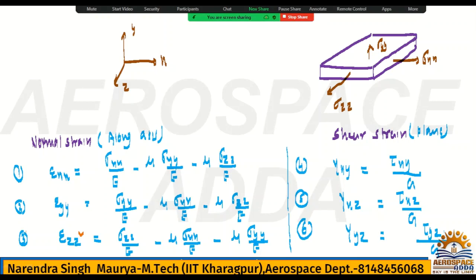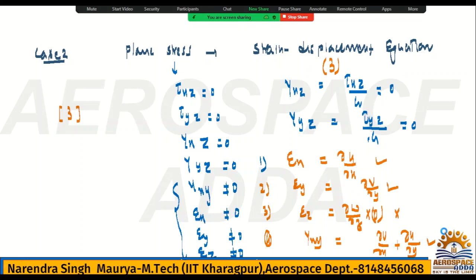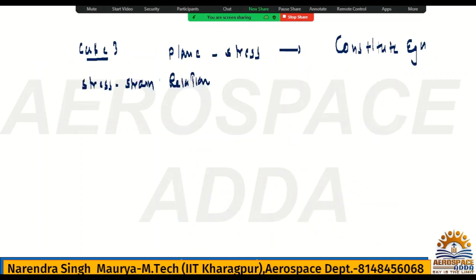So how many stress strain relationships may you have? You may have here, check. For the 3D I'm saying it's a 4, no? Gamma xy, tau xy by G will be there for the xy plane. Rest, epsilon zz will be there, epsilon yy will be there, and epsilon xx will be there for the plane stress condition. Yes. So for the plane stress condition, we will have this value.